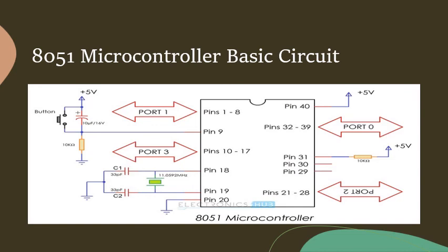The reset circuit of 8051 microcontroller consists of a capacitor, a resistor, and a push button, and this type of reset circuit provides a manual reset option. If you remove the push button, then the reset circuit becomes a power on reset circuit.